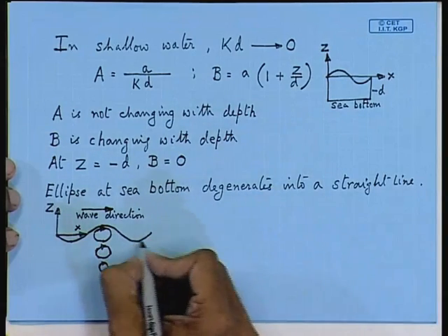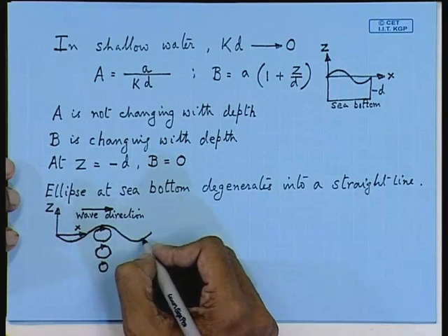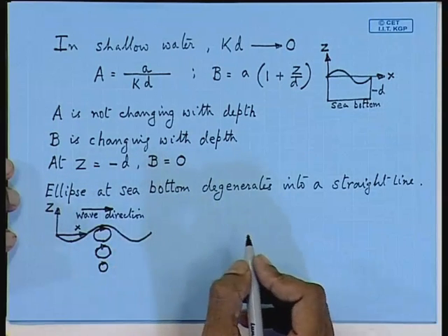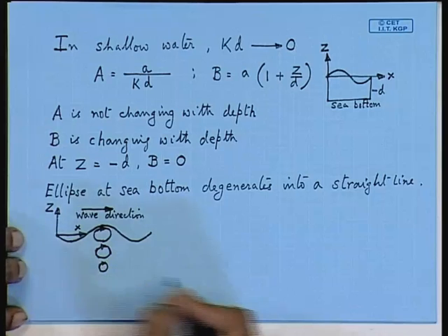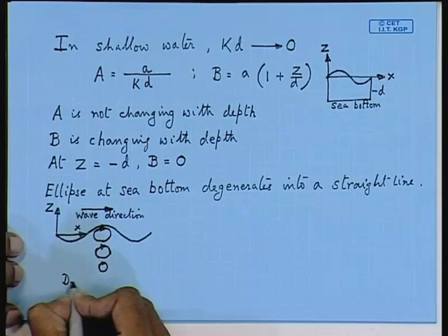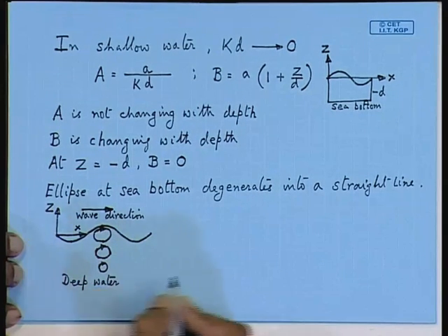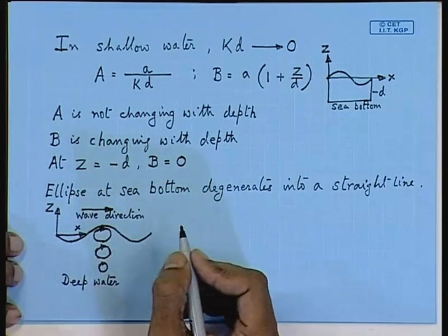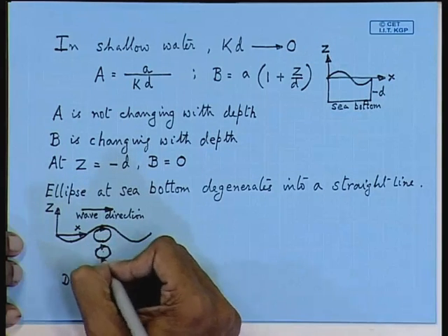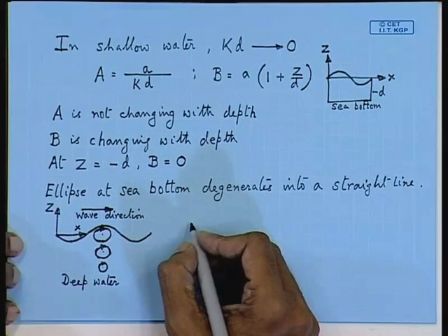Similarly, in a later diagram you will find, suppose you are on the trough of the wave, you are likely to be moved towards the crest and then you will get thrown away. So, that is the dynamics. Here we can distinctly see that in deep water the paths are circular, but their radii are constantly decreasing. Next, let us come to the intermediate waters.